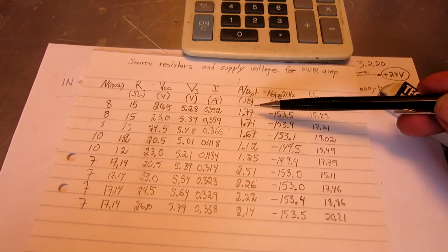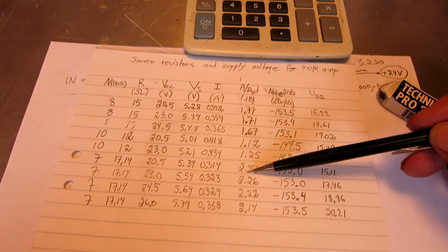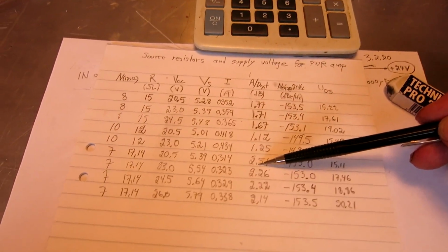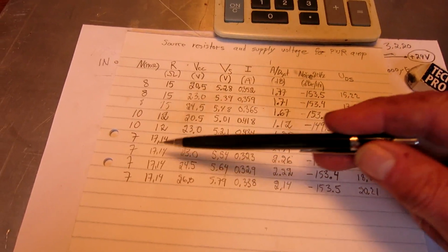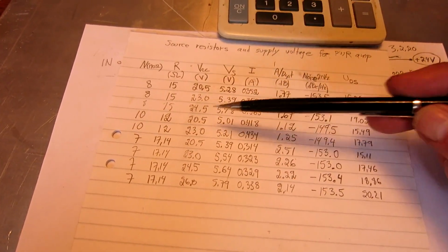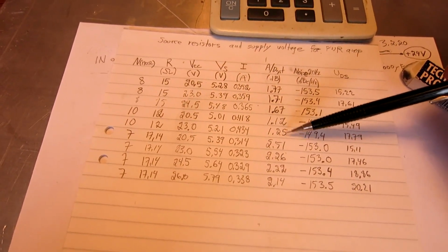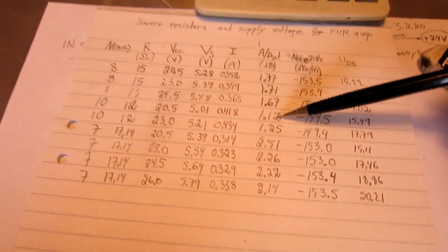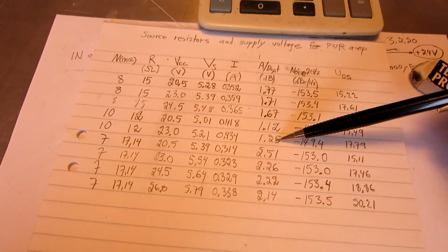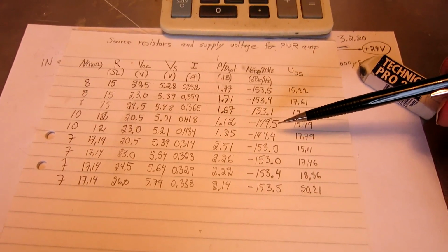So the margin becomes larger when I have a larger resistance on the source, and with a smaller source resistance the gain is higher. It means the margin to saturation of the AD is lower. The noise varies quite a lot.